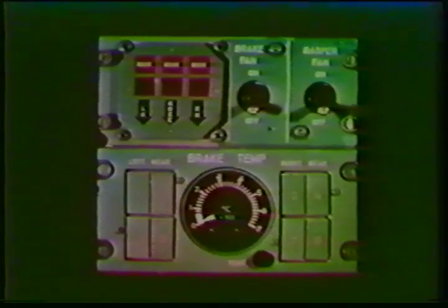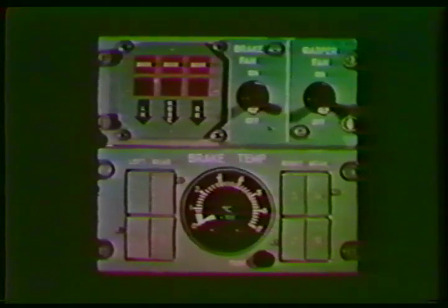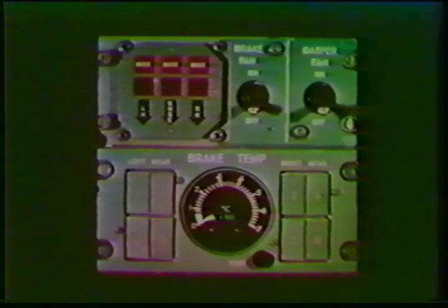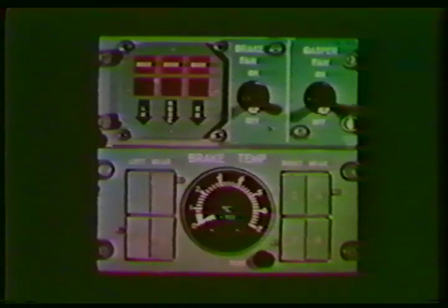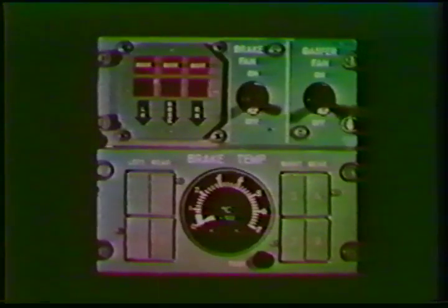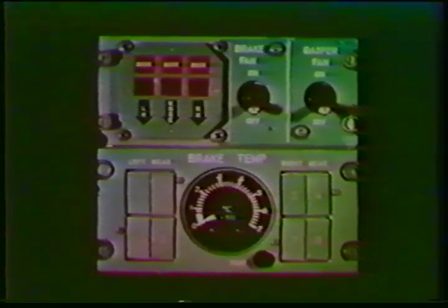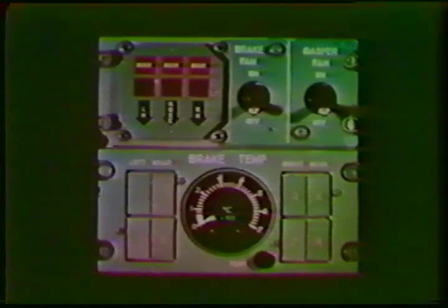A brake temperature monitoring unit located on the second officer's panel is equipped with an indicator, 8 amber warning lights, and a test switch. The brake temperature indicator displays the temperature of the hottest brake. When a brake hot light is pressed, it will read the temperature of that brake. An amber brake hot light will illuminate when the temperature of the brake reaches 185 degrees centigrade. The test switch tests all brake hot lights, and the brake temperature indicator shows 250 degrees centigrade above the hottest brake.